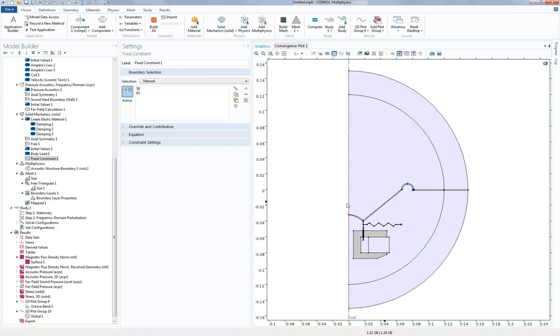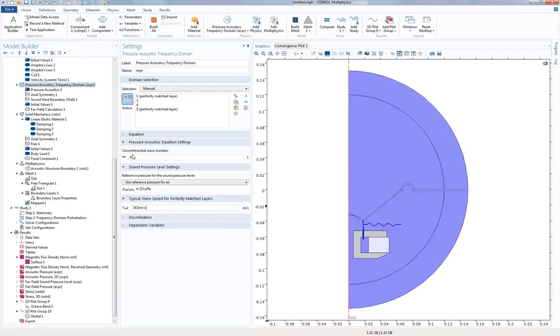One thing you can actually do in 2D, should you want to, is you go to pressure acoustics and you set a non-zero circumferential wave number. This lets you model phi directional modes with non-zero mode numbers as well. But if you want a true 3D geometry, you need to model it in 3D. I'll try to answer one more question before going back to the presentation.